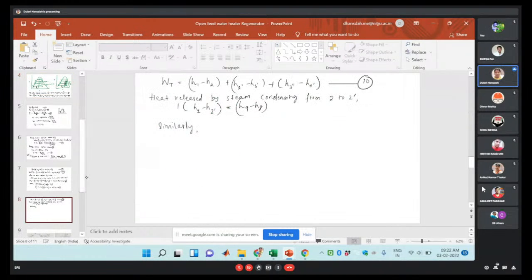So here I can write down that for 1 kg of steam, h3 minus h3 double dash is equal to 1 into h7 minus h6. So the heat released by the steam condensation is utilized to increase the temperature of the feed water. So this will be the equation: h3 minus h3 double dash is equal to h7 minus h6.